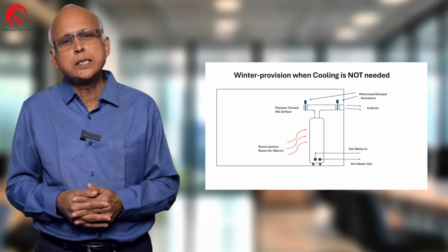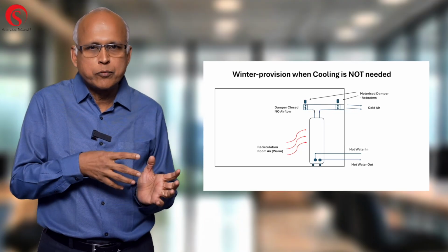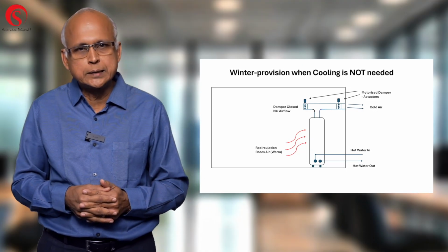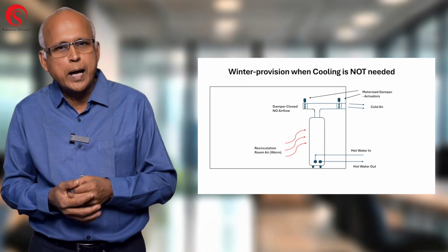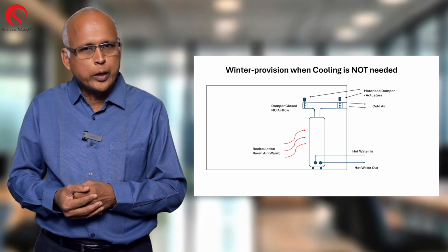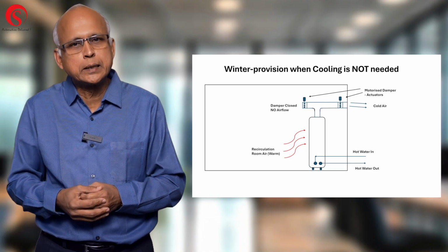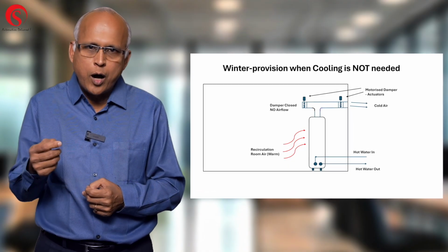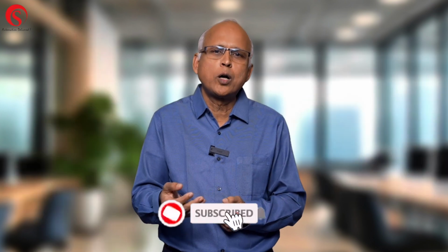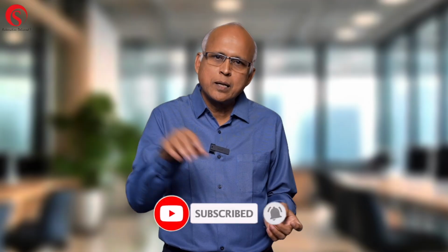One way we could look at is in the outlet air itself from the evaporator, before where the ducting is connected, plenum and all is there, we can very well give another branch and totally duct out the cold air during winter time. We can put a damper actuator there, PLC programmed, automatic, or it can be controlled manually also. So whenever you don't want the cold air to come inside the space, that damper actuator will open, throw the cold air out. So this is something practically we have done. So this is very much possible.